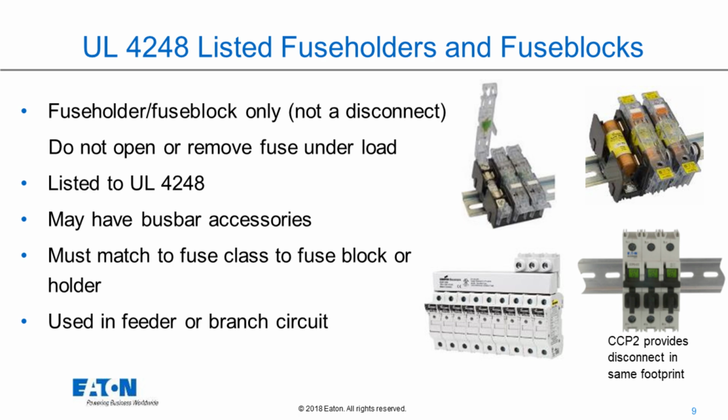Fuse blocks and fuse holders, UL 4248. These are not disconnect switches. These are just what they say, fuse blocks and holders. They're not to be opened under load or fuses removed under load. They may have bus bar accessories, like the device on the lower left has a 9-position array of modular holders.